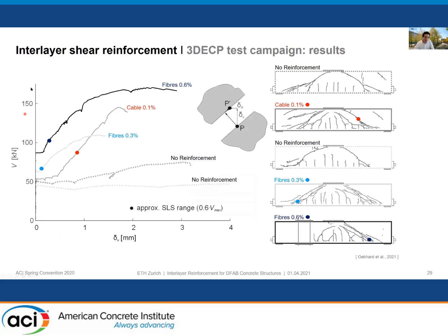Here we were selecting the point of the cracks with the largest opening and plotting it over the force. We are not plotting the crack opening itself, but the vertical projection of the crack opening. What is important here is that with the cable reinforcement, as soon as we have the shear crack, we need a large crack opening to activate the cable because it's a smooth cable.